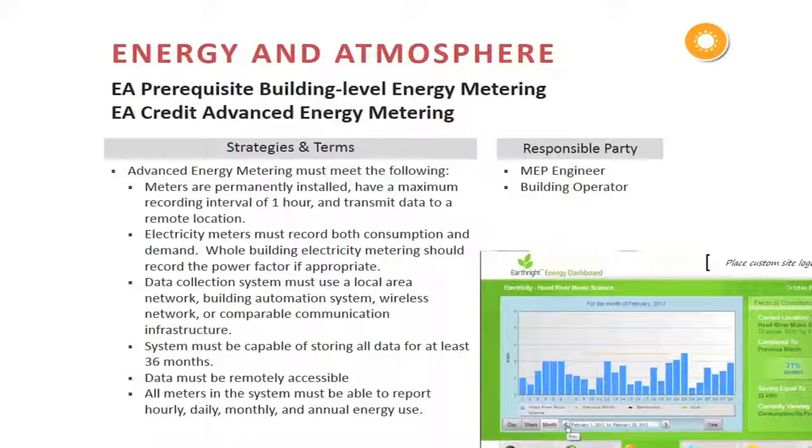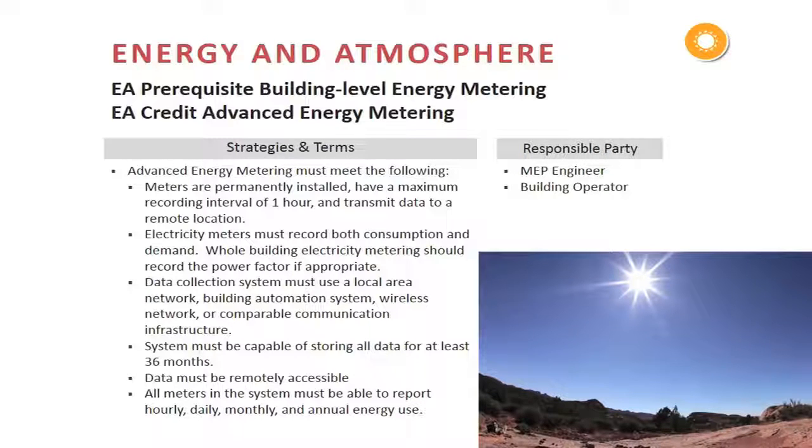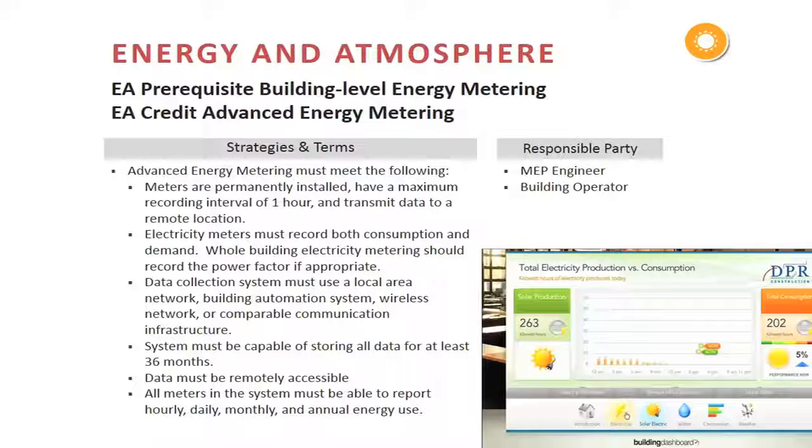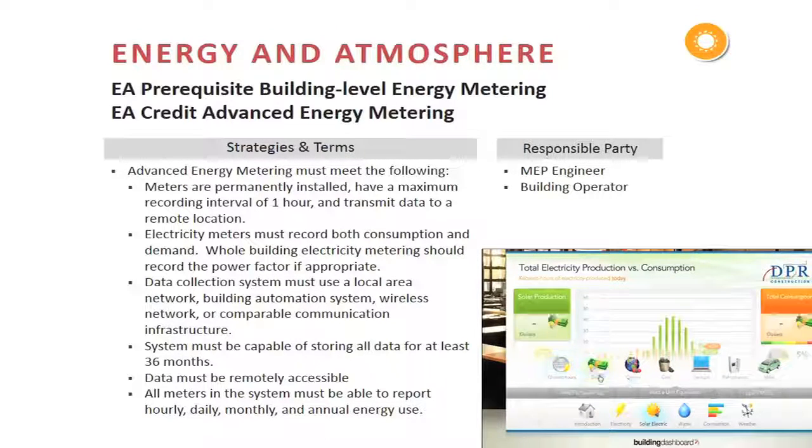So say that you had a really hot summer at your building. It would be inappropriate the next year to record your energy performance during that same summer period and say, wow, we've reduced our energy use by 10%, and pat ourselves on the back. Well, it's hard to say that that was due to the building performance, or if it was due to a milder climate during that same period. So averaging the 3 previous years helps to normalize that data, so you're using better information.